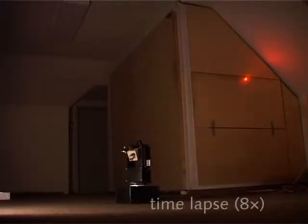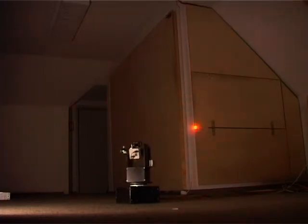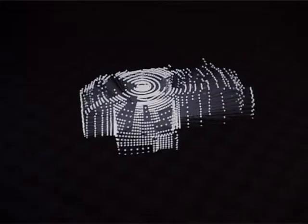When the PTZ camera is positioned at the architectural site, a full automatic self-registration is carried out. For registration, the PTZ camera samples the depth of the environment using the attached laser module. To avoid unnecessary motor movements and resulting long registration times, the sampling is not carried out uniformly along the hemispherical sampling space of the PTZ camera. Instead, an adaptive multi-resolution sampling is carried out.